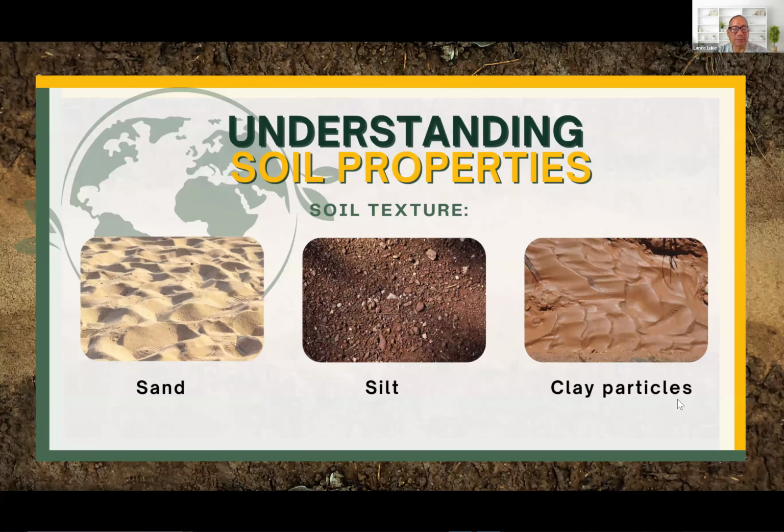The explanation of those is that sand is coarse particles, high drainage, but low water retention. If you're at the beach and you see the wave coming up and you see the water on the sand, if you look long enough, the water just kind of disappears. What happens to it? It sinks into the sand, and that's because of the high drainage. So the sand does not retain water. It just lets the water drain through.